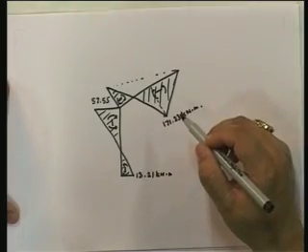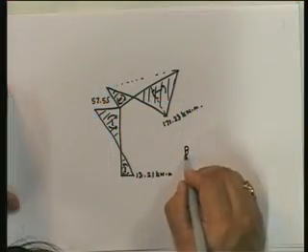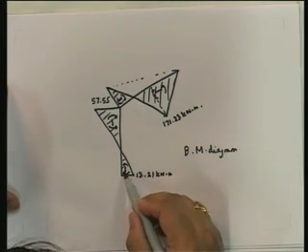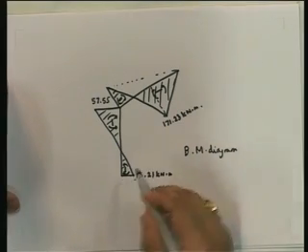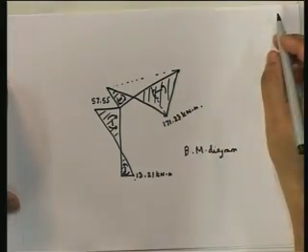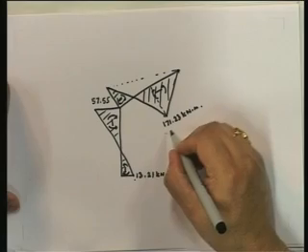the bending moment diagram. I'll leave it up to you to do. Remember, I told you that I am not going to be doing equilibrium for you. Once I've got the support reactions, you should be able to generate the bending moment diagram and shear force diagram for any member. Okay, and I've drawn the bending moment diagram here. The bending moment over here has to be 13.21 because that's the support reaction. The bending moment over here has to be 0 because at this point you have a hinge, so you cannot have a moment. And if you look at this, what happens here?